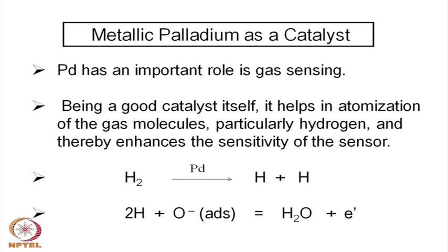If one can load the surface with very fine particles or fine islands of metallic palladium, that helps in the catalysis and adsorption, and in the process enhances the change in conductivity in presence of different gases. The atomization reaction takes place, and then atomized hydrogen reacts with the adsorbed oxygen ion and produces H2O and an electron.